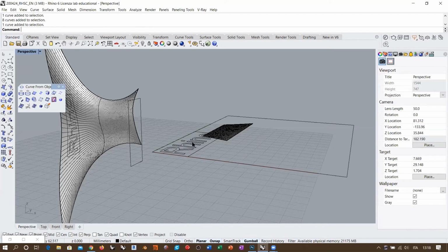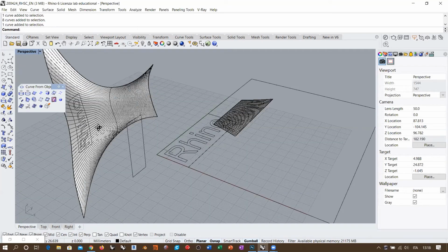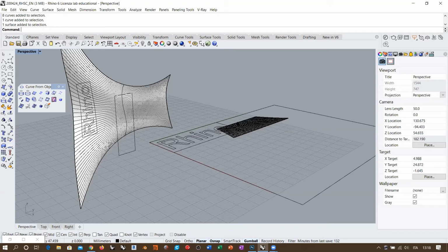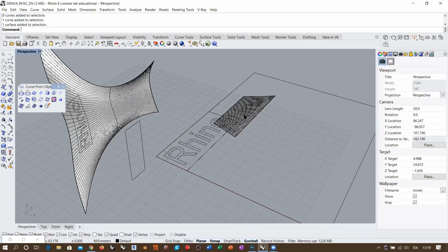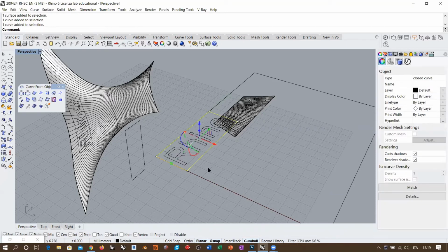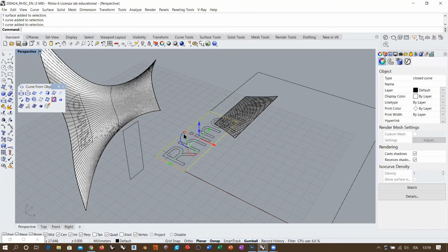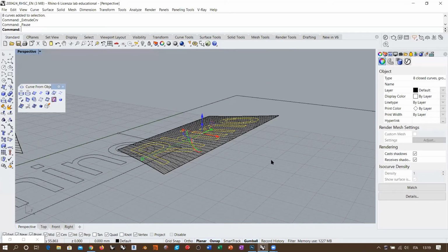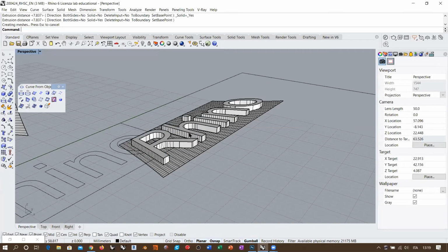So for example, in this case, if I wanted to apply a three-dimensional text on this surface with this regular behavior, I would apply a UV curve to determine this area, and then apply a UV curve to determine this area, and then apply a UV curve to get this text right here. And then I will take this text and extrude it solid, in order to give some thickness to the text.